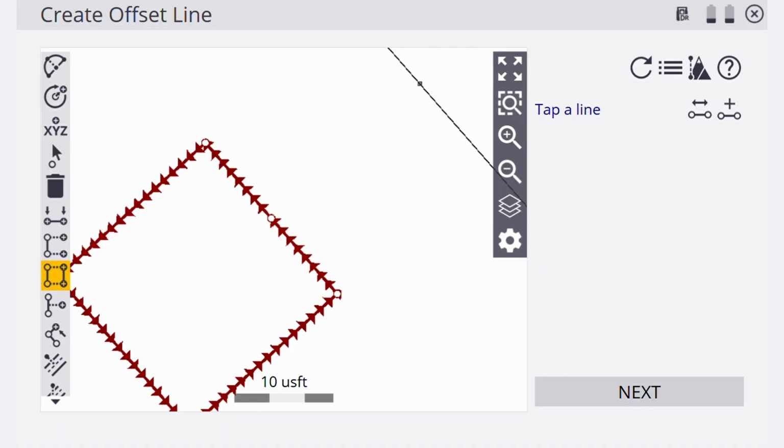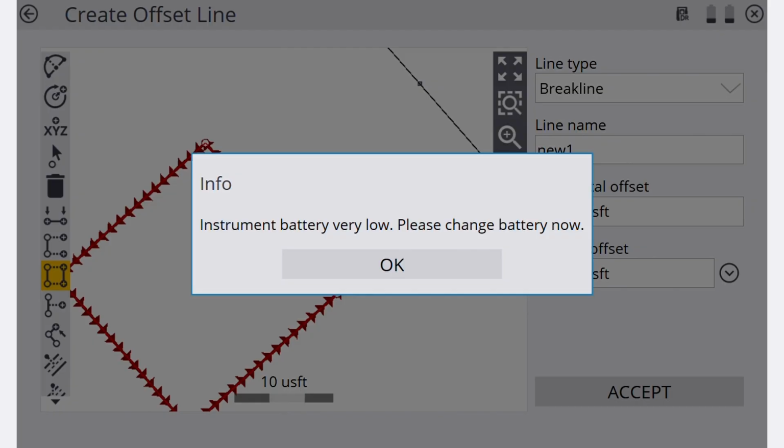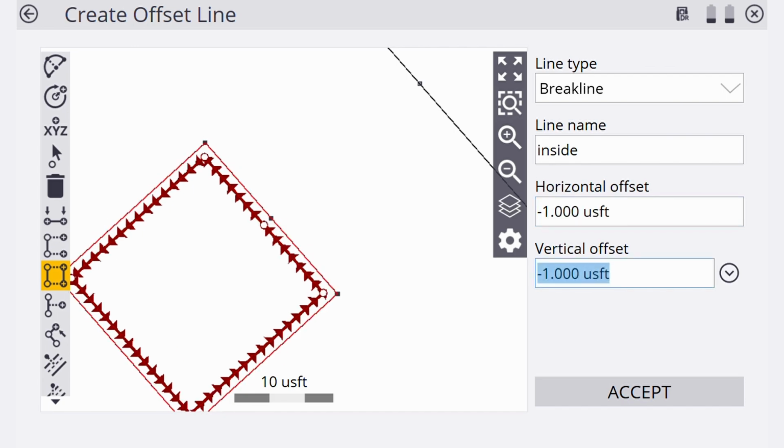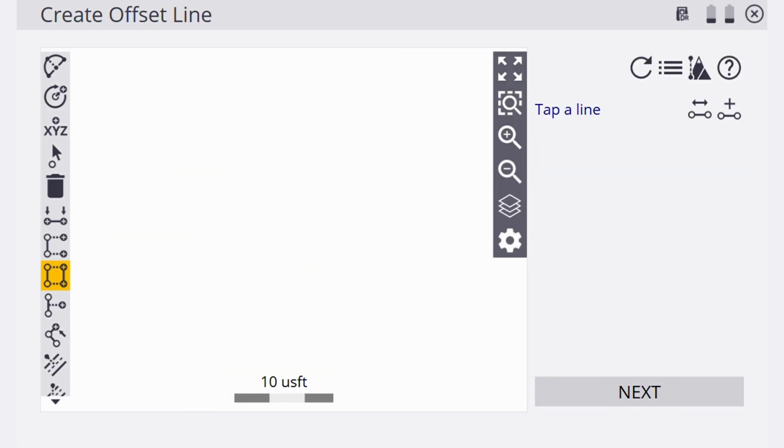So then we're going to select that line again and hit next. We're going to click on that, and then we're going to go over inside. This one's going to come over. We're going to make it 20 by 20. Maybe we'll come over about a foot, bring it over, and we're actually just going to carry that flat, straight across flat. That's our nice thickened edge. So we're going to hit accept.